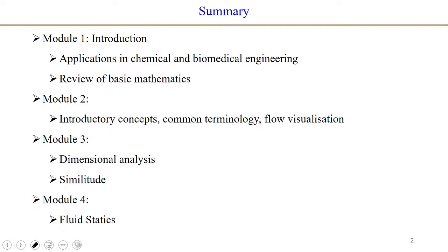we have macroscopic balances, where we first derived the Reynolds transport theorem, using which we can relate any extensive property of a system from system formulation to a control volume formulation, and using this we have derived the mass conservation, momentum conservation and energy conservation equations for integral analysis. So using this analysis we can find the integral quantities, such as the total force on a fluid, etc., or the drag force by a flowing fluid on a body.